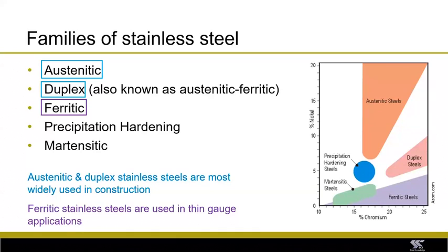Austenitics, they're the most important for today. So they're very ductile, they're reasonably strong. Your kitchen sink will be made of austenitic stainless steel, readily welded, and they work harden, so the strength increases as they're worked. Duplex, now this isn't a layer. Duplex is actually the microstructure. It's a mixture of austenite and ferrite. Now, these are stronger than austenitics, but not as easily formed.